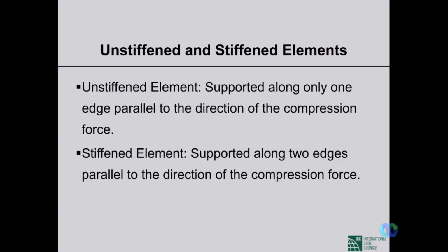Think about the compressive stresses on one flange of the I section and the direction of the force. Now, along that direction, in how many edges is the flange connected in the member? We'll show some figures, then it will be more clear to you.